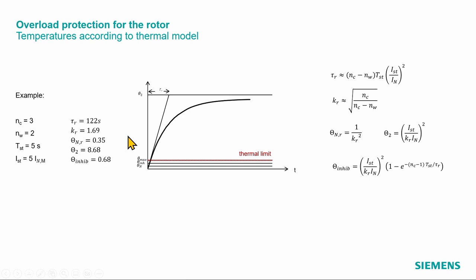And it's a little bit interesting, because if we think about the temperature when we have the nominal current flowing for the stator, we are around 83% or 90%, depending on the K factor we have there. And this is much higher, so we are relatively close to the maximum temperature as regards the stator. For the rotor, we are far away, as you see.